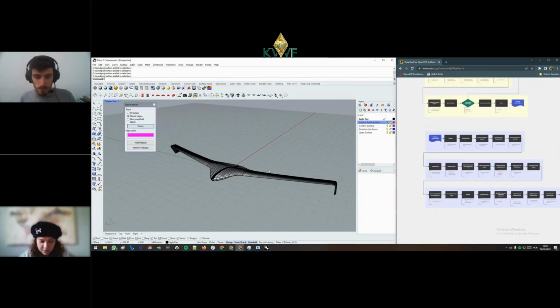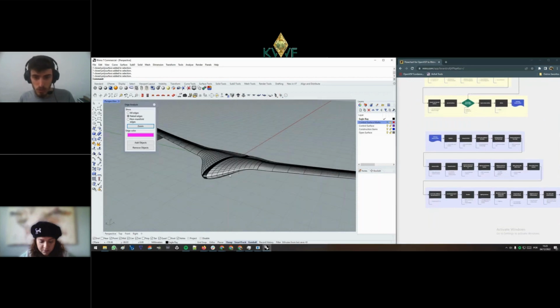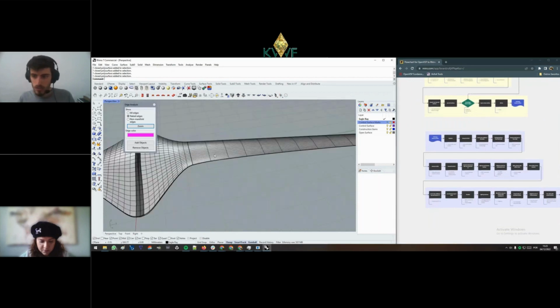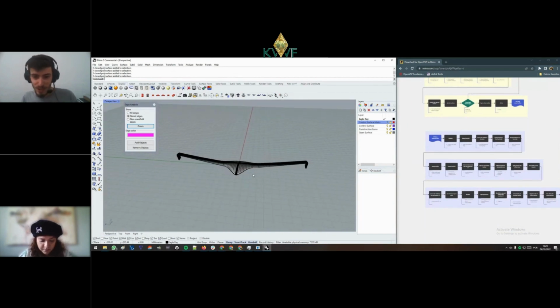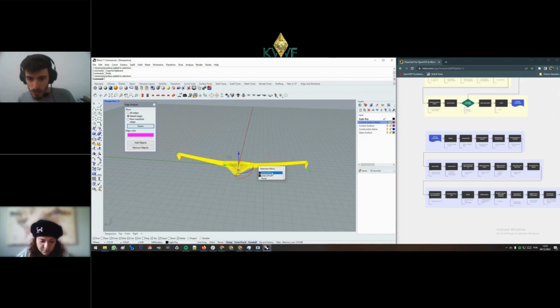So to cut out the control surfaces, we will start by undoing the closing we just did. I'll keep the closed surface, I'll just copy one and change it to the open surface here. This is the body we'll be working on now, and I will explode.